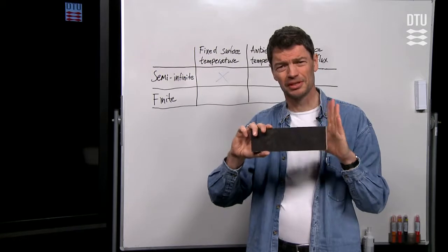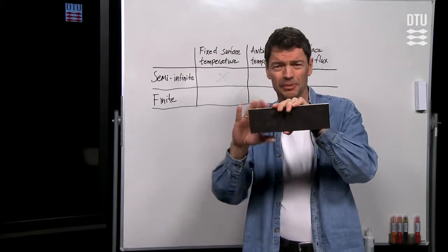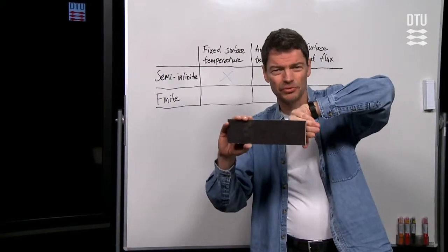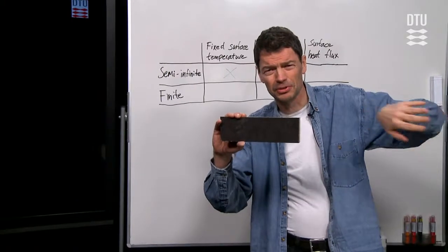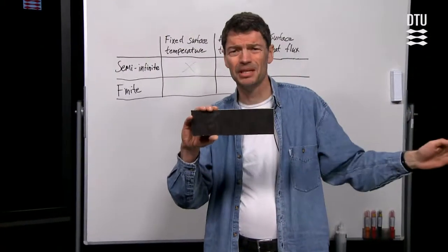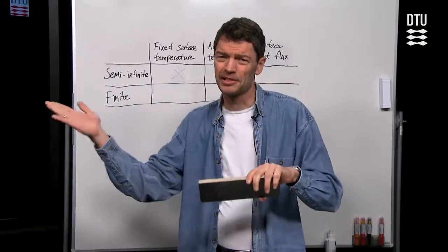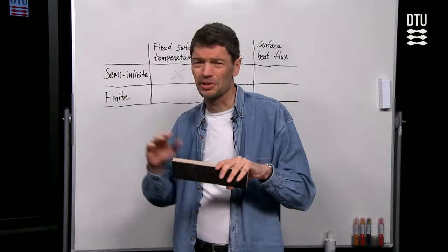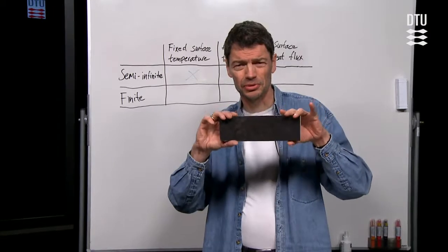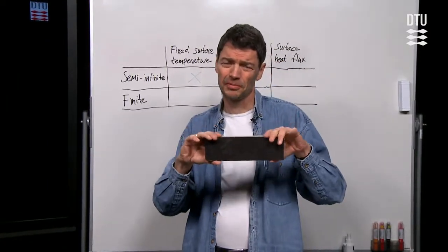But you could also consider a situation where you have a surface on the left-hand side, and that's a little bit superficial, but if there is no end to the material as we go to the right, it just projects infinitely. That's the semi-infinite body. It's superficial, yes, but for the mathematical solutions we're going to show today, it's easier to work with such solutions. So that's actually our starting point, despite the fact that the case is somewhat superficial.